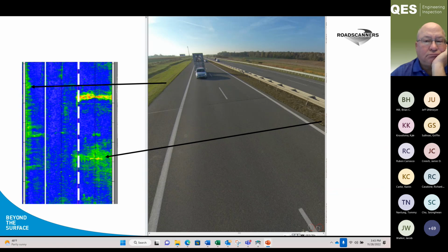So instead of starting to detect stripping, the idea we've been discussing in many countries in Europe is that you should find the areas where water is getting into the pavement and work with the drainage system, because then you can probably buy 10 more years by keeping the system dry, since in most cases stripping needs water. If you keep the drainage system okay, you don't have a stripping problem. So next slide.